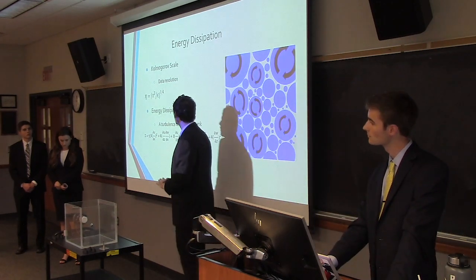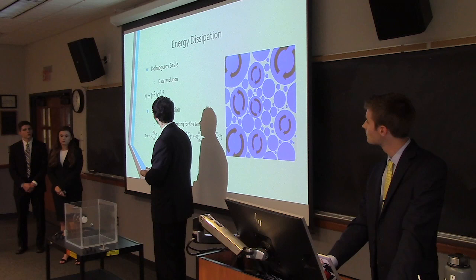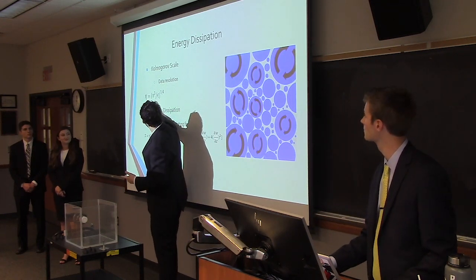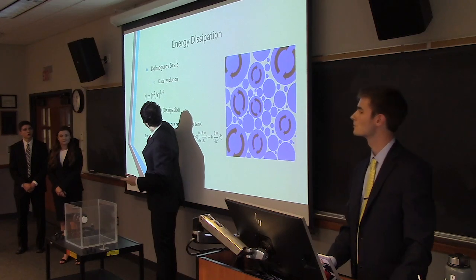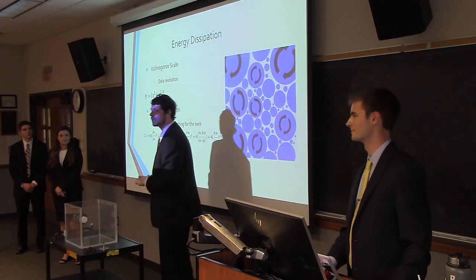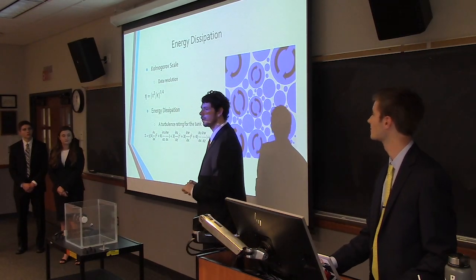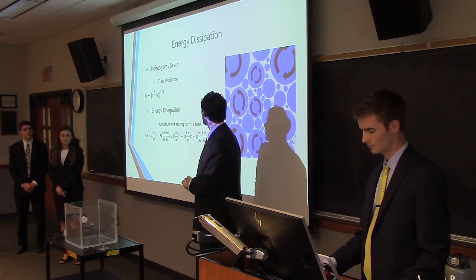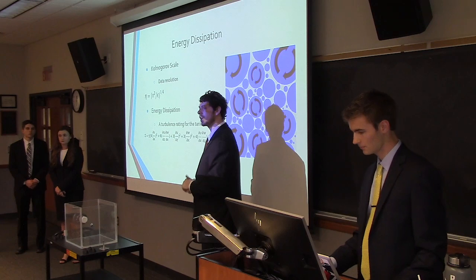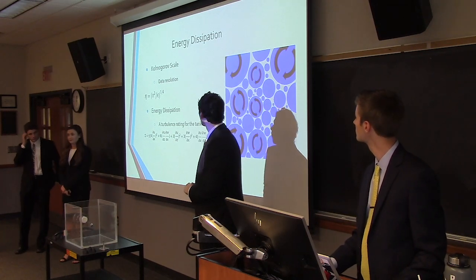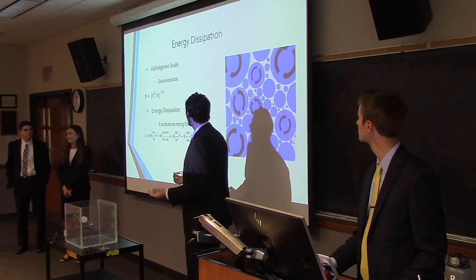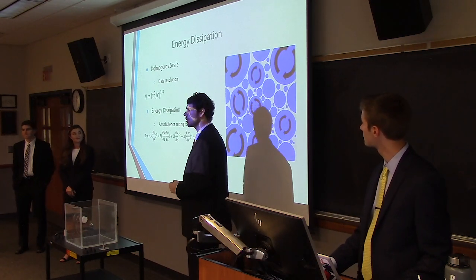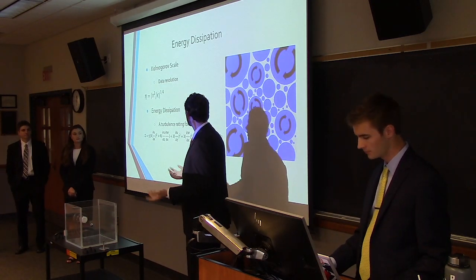Unfortunately, it's a back and forth process where we want the energy dissipation, which is this variable here, but we also need the Kolmogorov scale, which is here. So you need to do some sort of correlational data analysis, or some fluid simplifications to be able to estimate it, and then go back and test and see if that's a reasonable measurement based on PIV data.